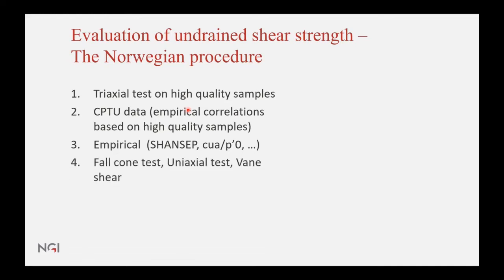And maybe the data that we use the least for a design profile would be fall cone tests, uniaxial tests, and even vane shear tests, because vane shear tests don't work really well for Norwegian clays. With clays of low plasticity, you have some progressive failure mechanisms along the vane